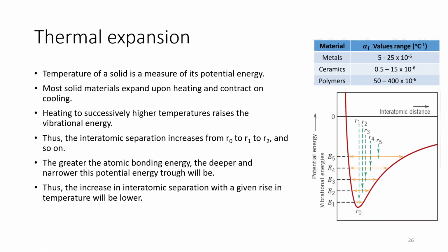Next property is thermal expansion. So the temperature of a solid is a measure of its potential energy. Most solid materials expand upon heating and contract on cooling. The heating to successively higher temperatures raises the vibrational energy. Thus the interatomic separation increases from R0 to R1 to R3 and so on.